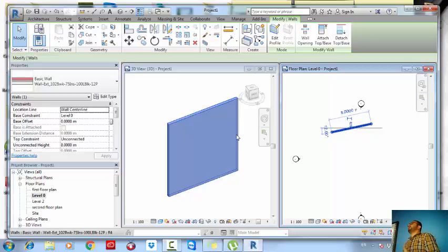In Revit you should always use the constraints, and it's better to connect your objects to the levels that you have. So if you are drawing on level 0, connect your objects on level 0. If you are extending your objects from level 0 to level 3 for example, don't give it 15 meters, set it to extend the object from level 0 to level 3.